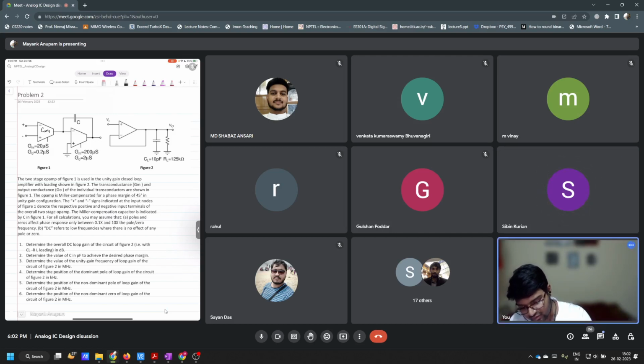Yeah, understood. That is a very good question actually. So you see, this is an approximation. We have understood it in this way, that P1 is appearing because this capacitor is being multiplied by this. And you say that P1 appears here and then it starts with 20 dB per decade and then P2 is at a very high frequency. But the question is very right: this P1 approximation holds only for low frequencies. At very high frequencies, this curve should not be like that, right?